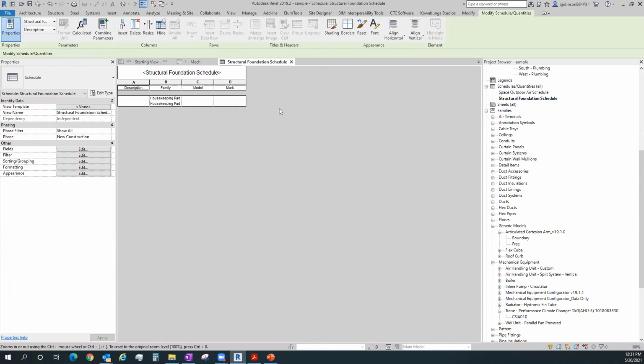An example of that would be in my previous job, I had a guy that was a young EIT-type mechanical engineer in training. He found a Dynamo script that said, I can take an architectural file and find all the fire rated walls and then go place a damper in those fire rated walls, which is inside my ductwork. So he read the description of it and said, that is fantastic. I want that because I have to go back and manually find and place upwards of 100 dampers in this large, say, medical building or office building. Every time we have this type of building, it takes me 2 days to go put dampers in. So he loved the idea that he found a Dynamo script that would do that for him.